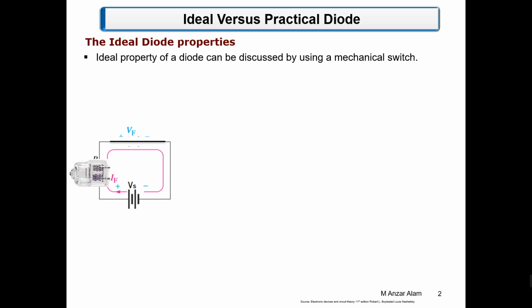So in actual circuits, instead of a resistor we use, I think this one is a 12 volt DC LED lamp. When this plus is connected with the plus of the lamp, and the minus is connected with this one, whenever the diode is turned on, the lamp will turn on. The maximum current will flow through the lamp, so the device will turn on. So it can be any load.